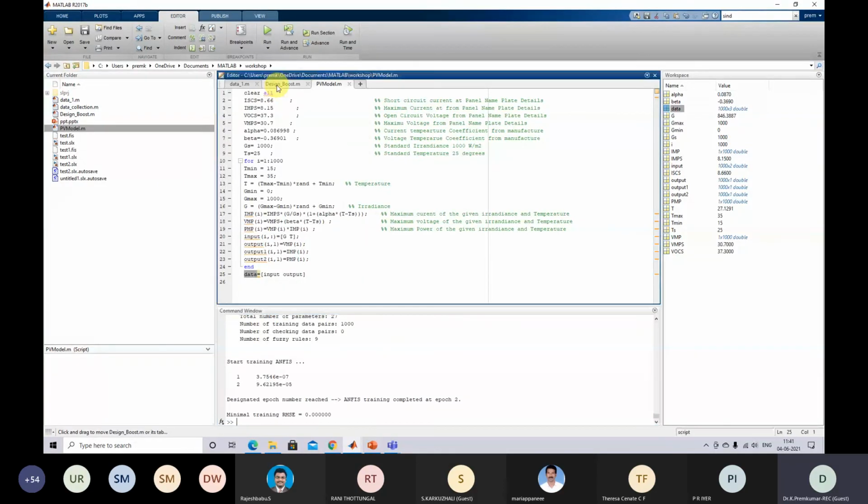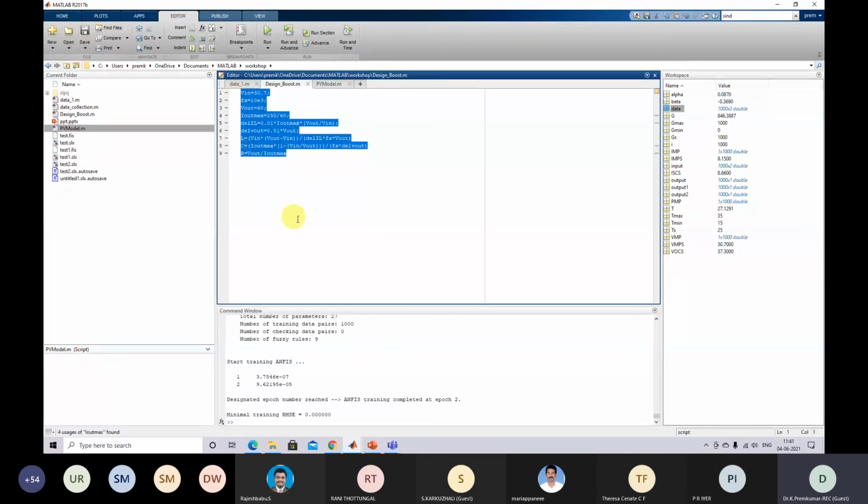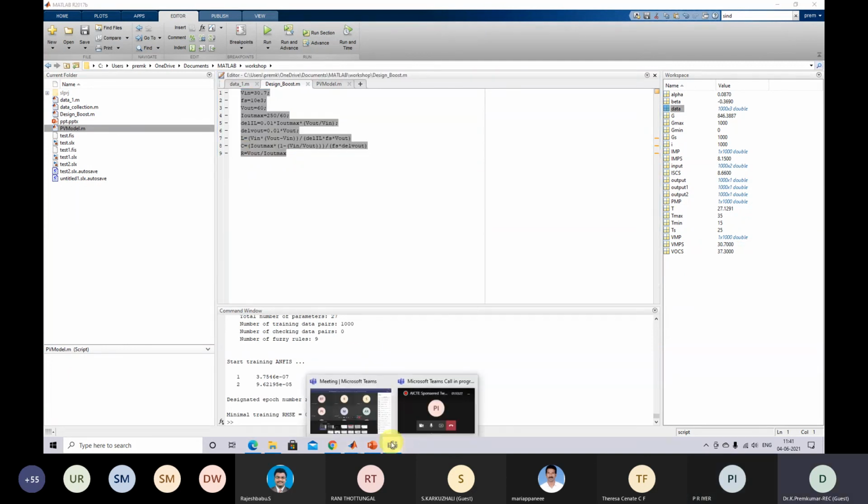These equations, you can see that, sir? Yeah, I can see. Unfortunately, I am on my mobile, so the pictures are very small. Okay. So this is the standard equation for designing the L and C for the boost converter. So based upon our power rating and input voltage, output voltage, and output load current rating, right? So here we have to design by using these formulas for the L and C. Clear, sir?